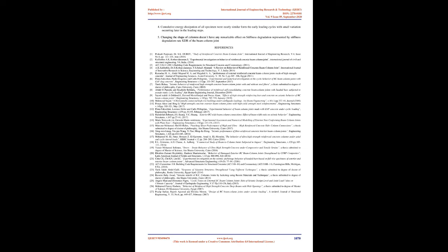Rapid strength decay produces significant adverse effects on the hysteretic response. To measure the ability of the beam column to maintain its carrying capacity in the post-elastic range, the loop peak load at maximum recorded level was compared to ultimate load of specimen. This comparison was quantified using the strength decay rate, SDR.